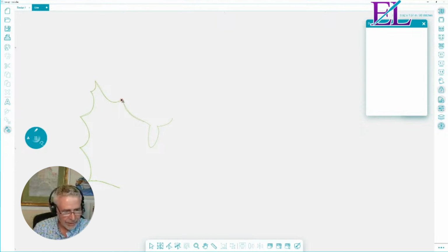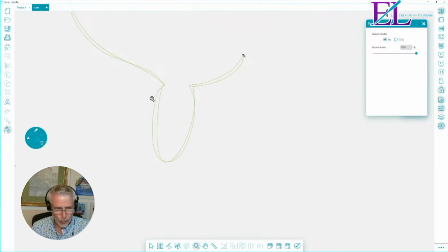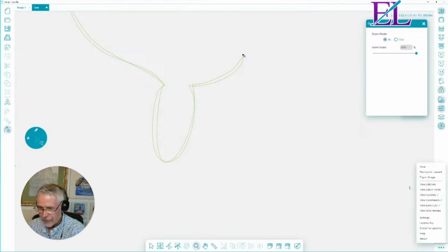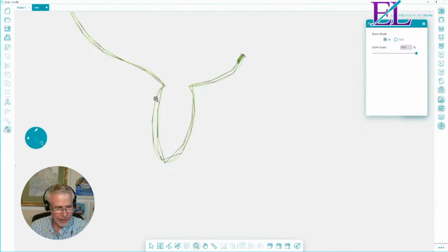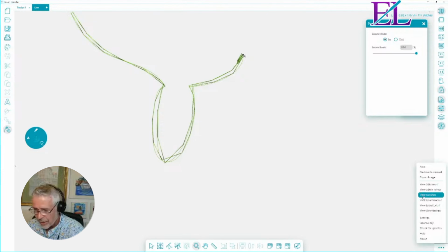So, there I can have a piece off a little bit. I can go here, I can come over here. And if I look at all of these pieces right now at 600%, it doesn't look too bad. If I zoom in even more, to like 2100%, you can see that there are huge gaps there. And if I go into my stitches and view stitches, it even looks crazier because it's going to show all the points trying to retain those lines.